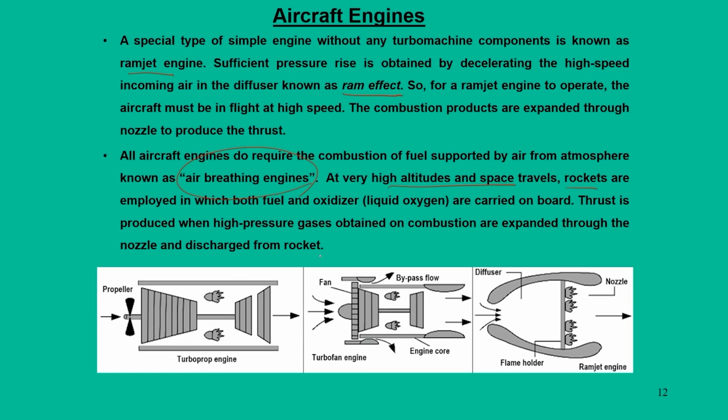So we require fuel and oxidizers separately, typically liquid oxygen, and thrust is produced when high pressure gases are obtained on combustion, expanded through the nozzle and discharged from the rocket. They are known as non air breathing engines or rocket engines. So rocket engines are not air breathing engines, they are non air breathing engines.